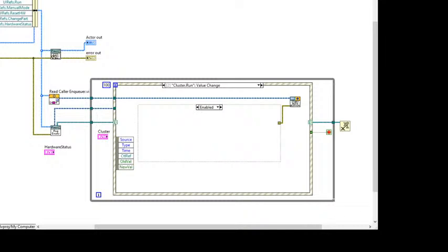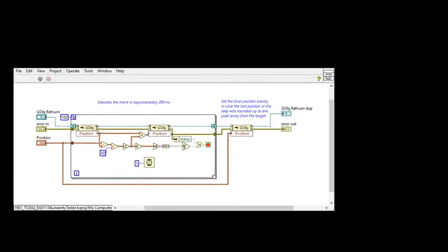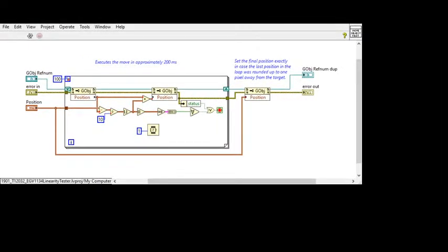Up to their VI real quick. Utility class. Okay. One of the nice functions that the LabVIEW UI toolkit provides you with is how to move an object, any global object, from one position to another. It takes a look at whatever the resting position is, you give it a target position, and it moves it there based on steps, timing between each loop.